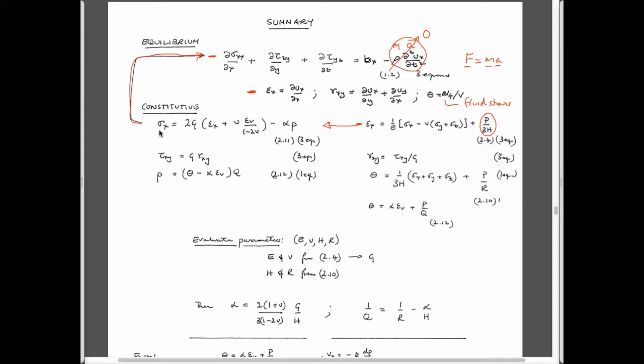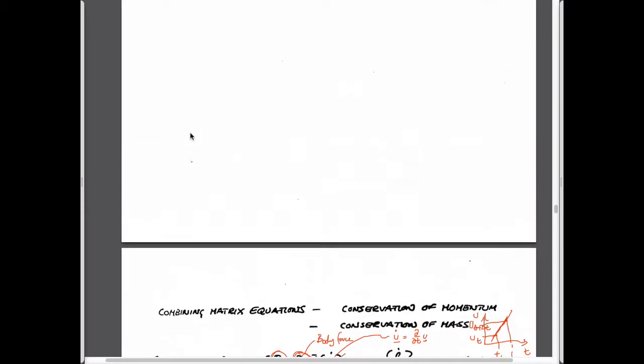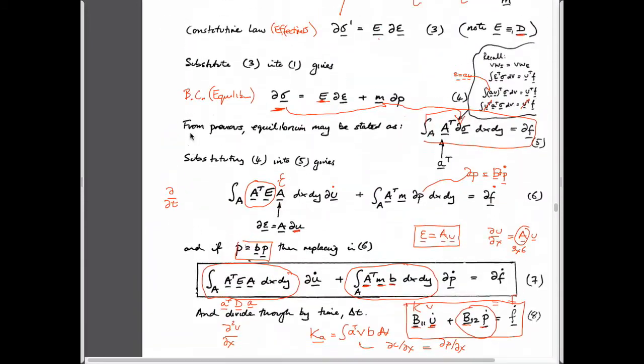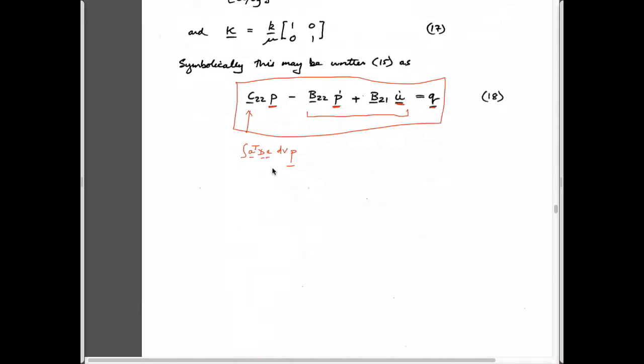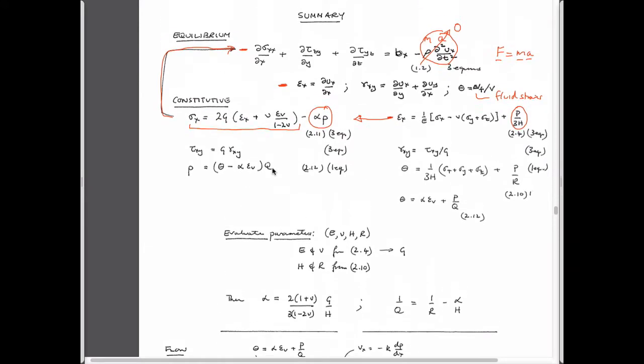So this is the constitutive relationship. It includes the effect of fluid pressure because strains and total stresses are linked, including fluid pressures, right? So effective stresses define strains. And so actually this is exactly what we did in the finite element equations, if you remember. It's the very first equation. Basically this, right? We wrote it slightly differently. But if you write it out discretely, then it's written in this particular form here.